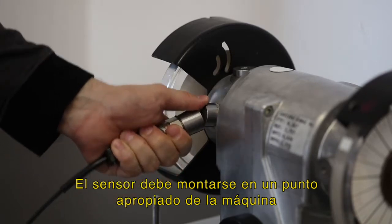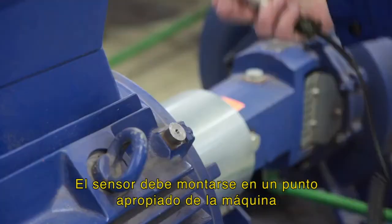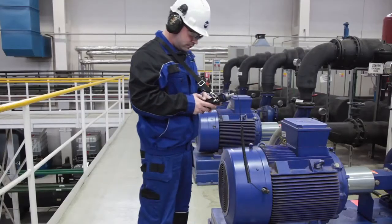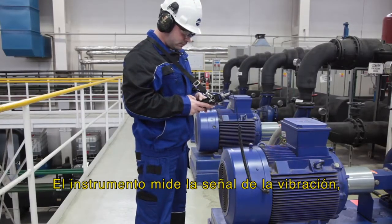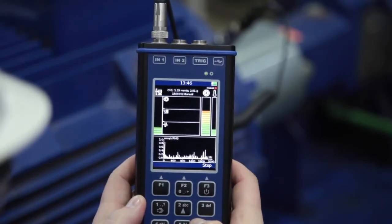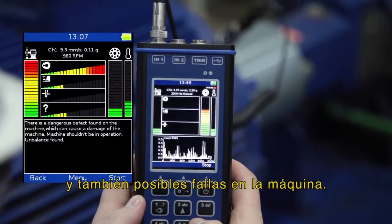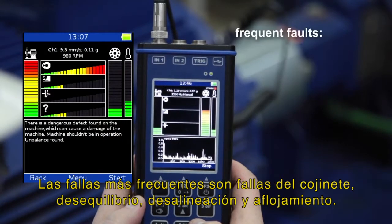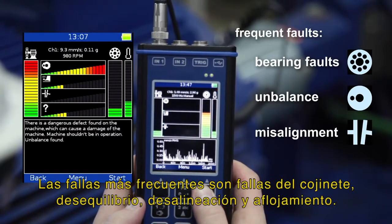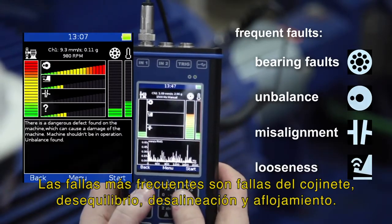The sensor needs to be mounted on an appropriate point on the machine, e.g. bearing housing. The instrument measures the vibration signal, tells you the severity of the vibrations, and also possible machine faults. The most frequent faults are bearing faults, unbalance, misalignment, and looseness.